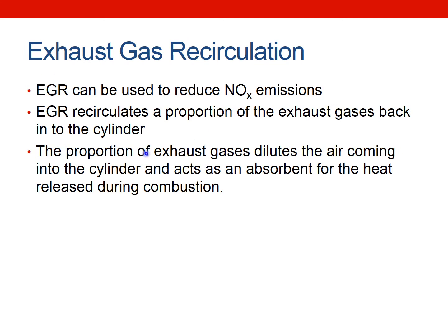Anyway, the proportion of the exhaust gases dilutes the air coming into the cylinder. So instead of having this whole new cylinder of fresh charge, you've got a percentage of exhaust gas, and because it's already combusted and oxidized, it can't be combusted again.